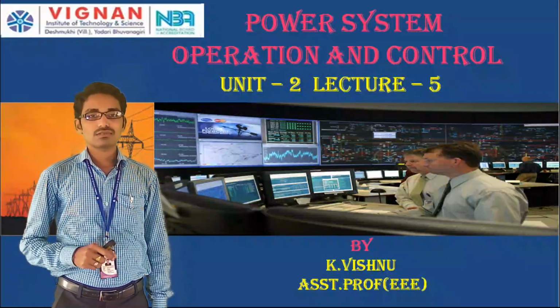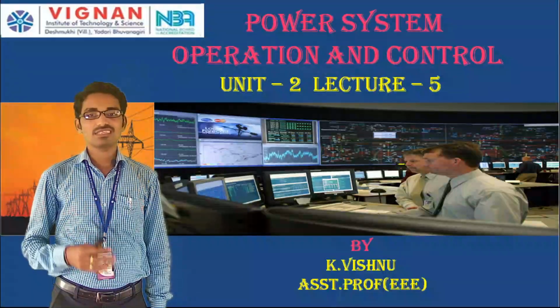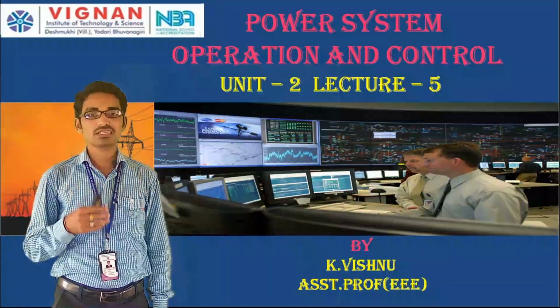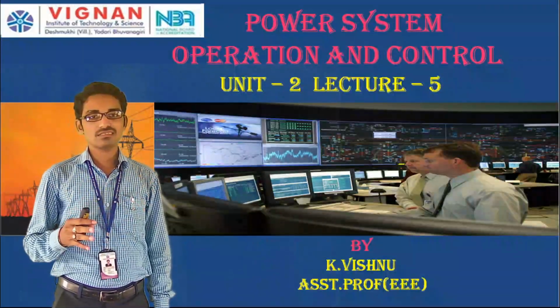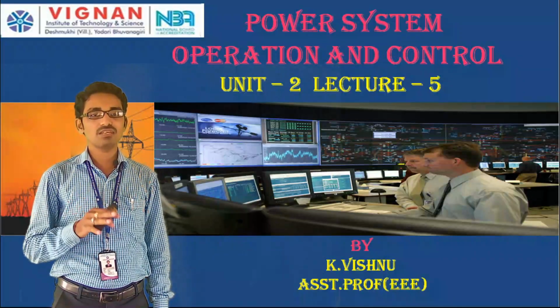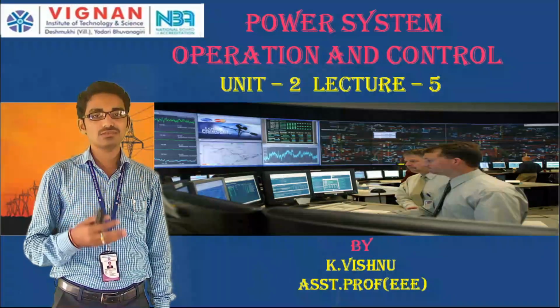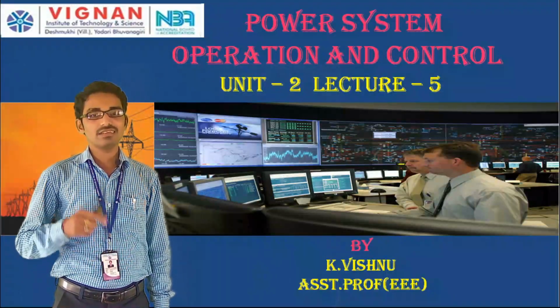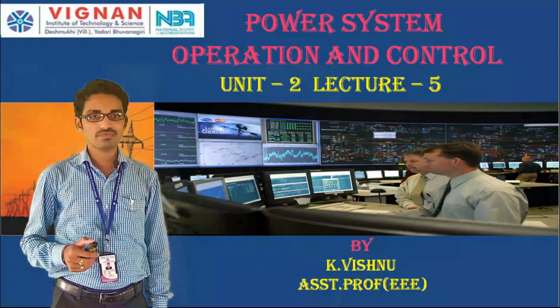We saw how to control the voltage with the help of a shunt reactor, a series capacitor and a synchronous phase modifier. With these three, we can control the voltage, either by absorbing reactive power or by injecting reactive power into the line at the receiving end.